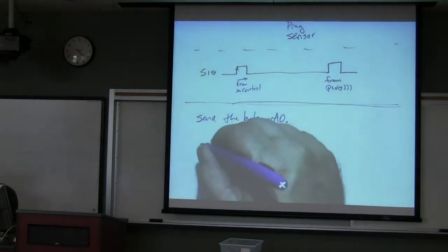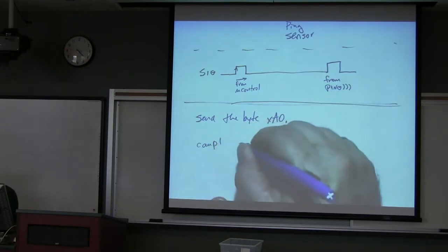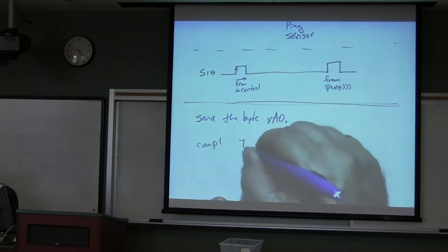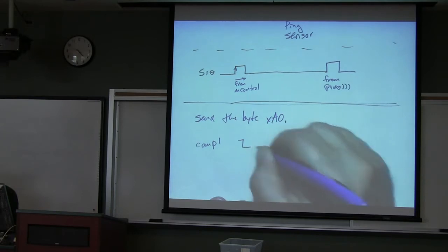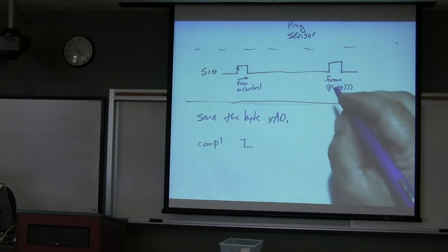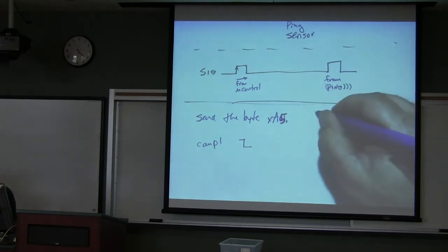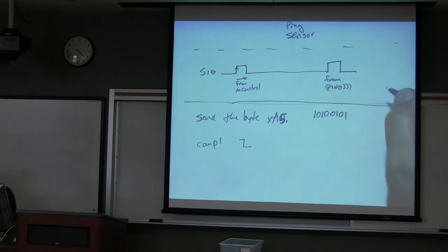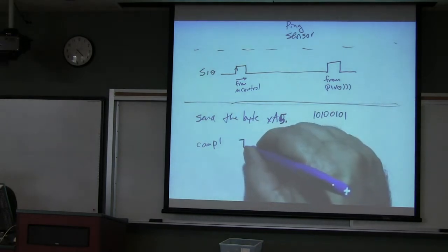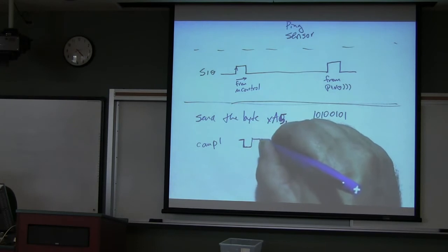So from computer 1, I'm going to send the start bit. Actually, you know what, I'll send A5. That looks easier. So that's the pattern 10100101. Wasn't that convenient? So it's going to send a logical 0 for the start bit. Then the next bit is going to be logical 1.